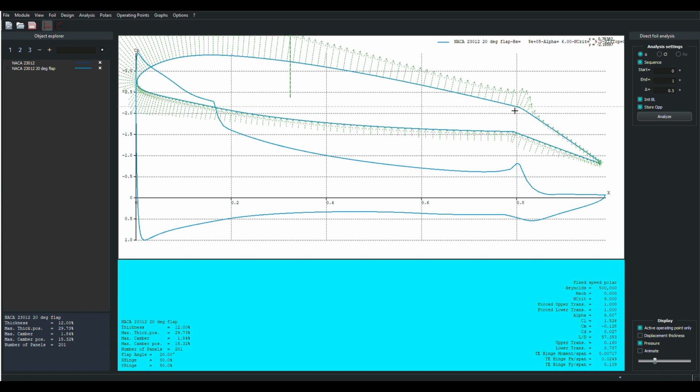I do not have that luxury here because we're flying both slow, with a thick airfoil and a big round leading edge on our flap. So you get messed up flow. And when Peter and I first saw it, Peter said, oh, flow through the gap. There's a hinge gap, high pressure on the bottom, low pressure on the top. Classic theory we've all been taught in school. Flow's going through the gap and causing separation, and it's going out along the wing. And I went, yeah, you're probably right, because it's a classic explanation of it.